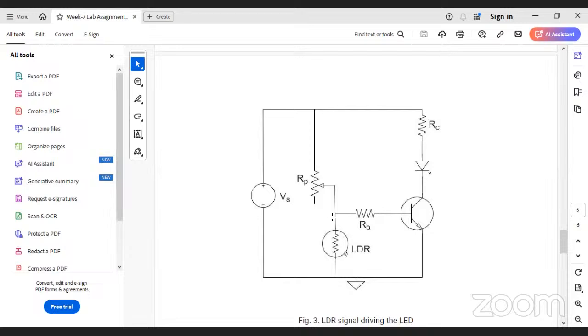Actually, ma'am, the response time of a multimeter is very slow, about 100 milliseconds. Having the sweep at 100 milliseconds or 10 milliseconds will cause a fluctuation in the multimeter reading. Even with a 1 second sweep, there will be a fluctuation every 1 second, and it is due to a glitch with the ADLM kit. Having it at 10 seconds will be better to take readings from the multimeter and the ADLM kit. Better you disable the repeated sweep, so that already will solve this issue.